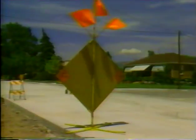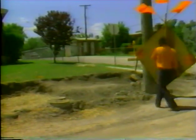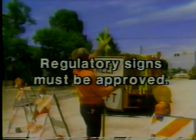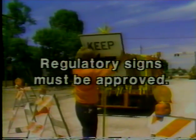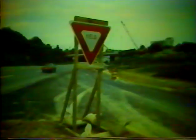2 more points about sign placement. First, see that the contractor covers or removes any sign that doesn't reflect the current roadway conditions. Inaccurate signing decreases respect and confidence in our traffic control efforts. And second, the contractor may not install any temporary regulatory signs without the approval of the agency that has jurisdiction over the project. Some common regulatory signs used in work zones are speed limit and road closed signs, as well as stop and yield signs. All must be part of the approved traffic control plan.